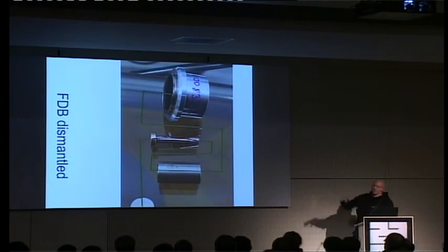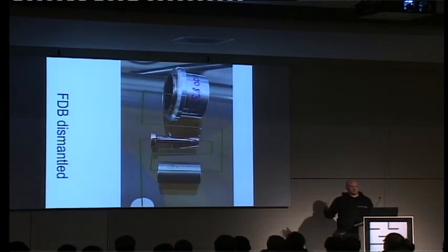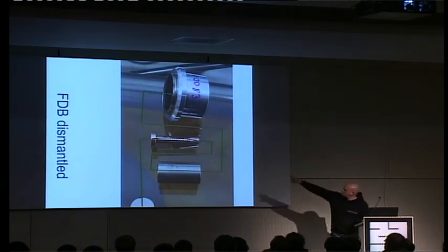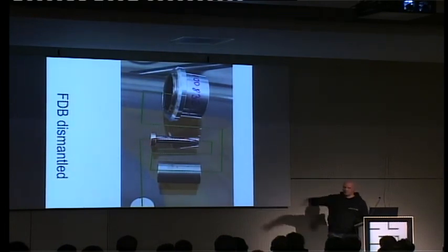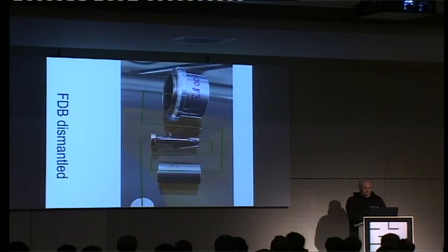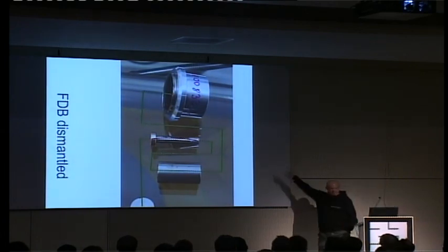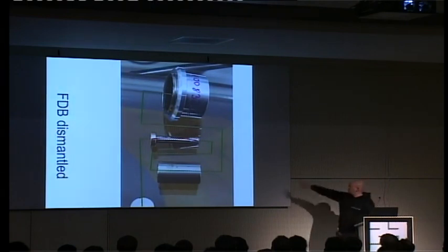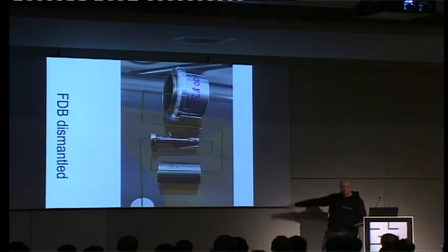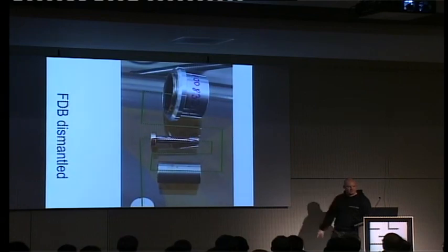This one died by bending it. There was too much acceleration force on the platter hub, and that bent this spindle pin, and that made the bearing stuck. So this is typical drop damage. On my slide, it says typical drop damage on this one. So you just imagine that, right?